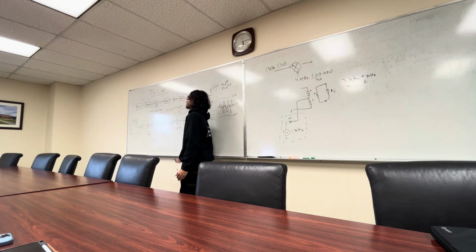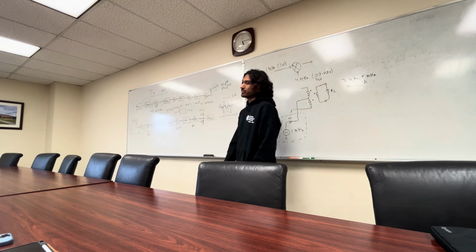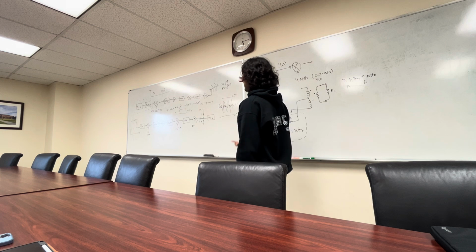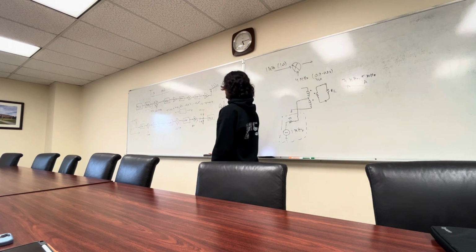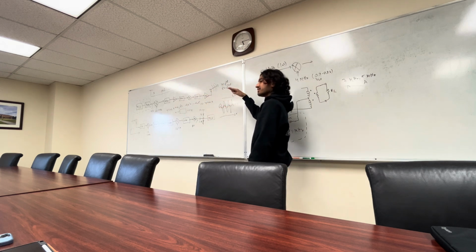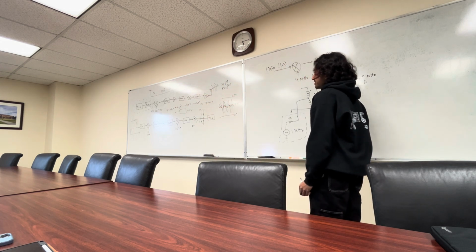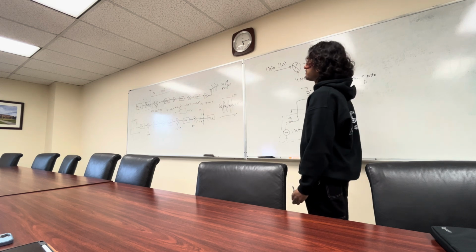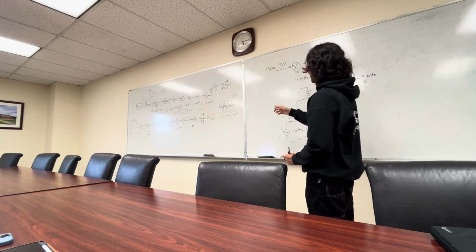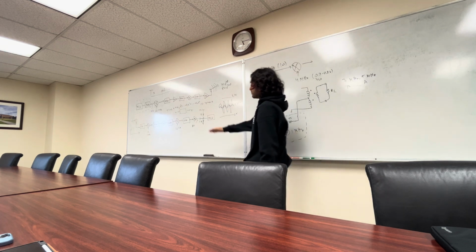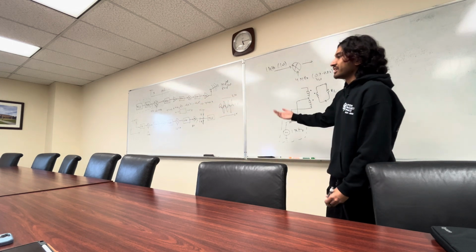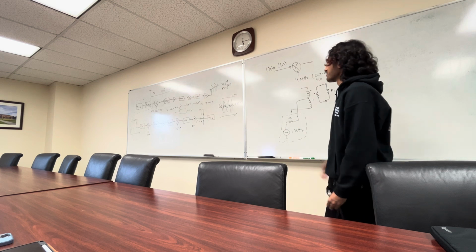You may ask, well, if it's going to attenuate anyway, why even have a large signal to begin with? The reason is the way the DAC works on the board: we only have so much control and precision over it, and it's much easier to have larger rail-to-rail swings based on our digital encoding. This is a way to have better mixer performance, and if you want, in this next module you'll have to replicate your MCU as something at 1.65 volts amplitude. You'll see that if you insert this buffer and the T attenuator, you'll get better performance at the output. So that's something you can explore.